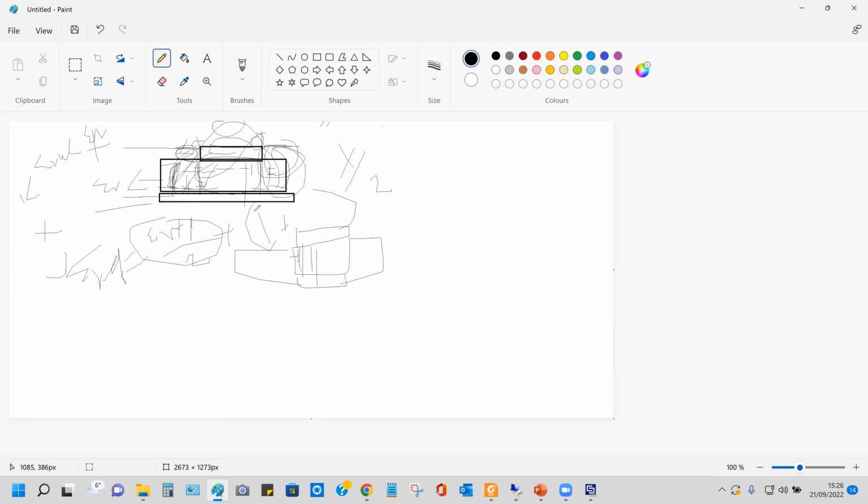So that's why they added this term 1 by W by H. It is heavily dependent on the width of the substrate and height of the substrate. So accordingly, this is a correction factor they have. Okay, epsilon r effective.